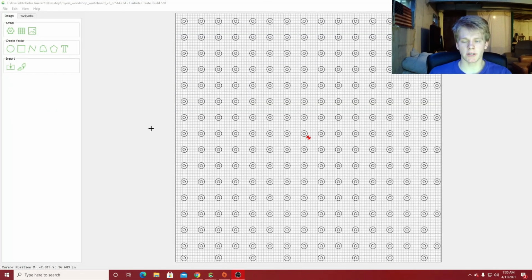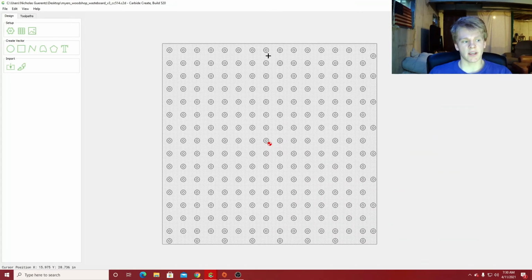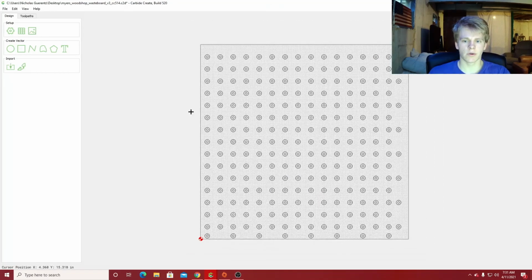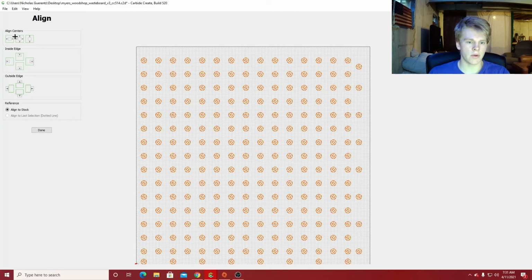Alright, so as I just mentioned, I'm going to make that spoiler board that sits on top. That's 23 7/8 by 24 7/8. My original plan was just to size down this job setup, but I realized I can't do that because when I originally made this, I made this 32 by 32, and so it won't properly line up. This new one's 0.6 deep, and we're going to center the lower left. This is MDF. When I resized this, I grouped everything together and recentered it.